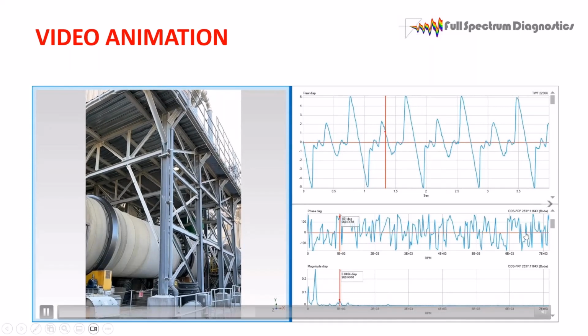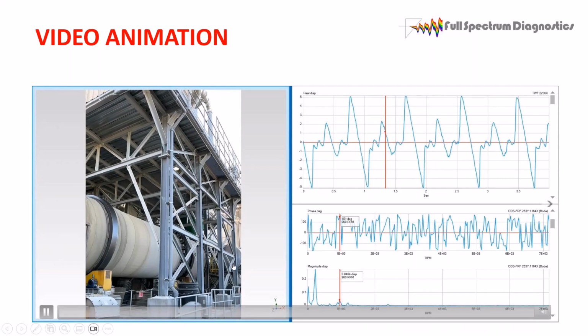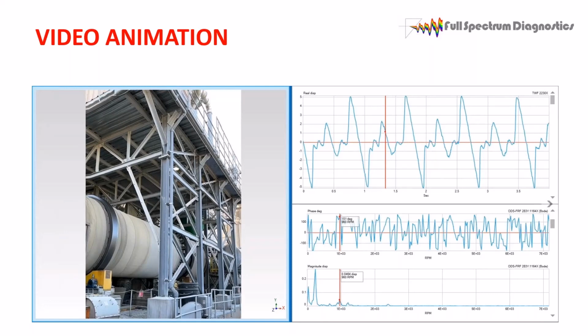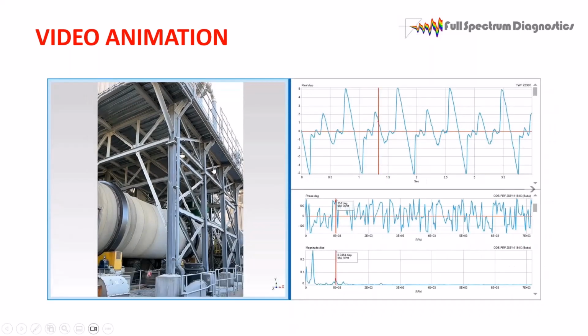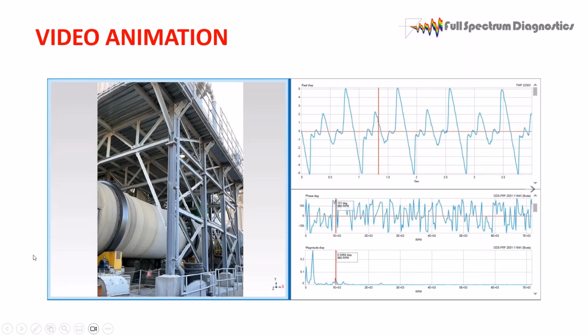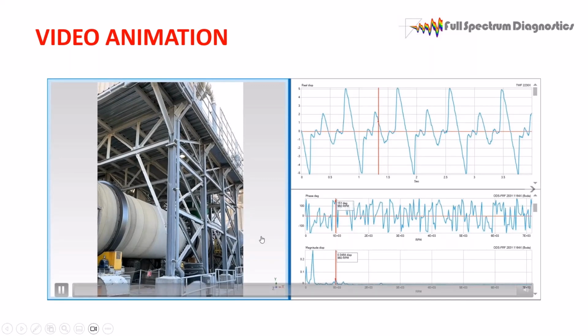This is the ODS FRF. It's slightly different. That was 340. This is 980. And here's where we see that crossing pattern twisting, just like we did before. They're out of phase with each other, but that's a mode shape. And here's a bounce. This is at roughly 982. And they're still out of phase with each other.